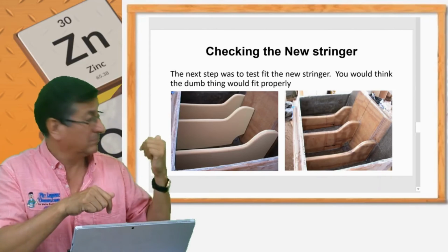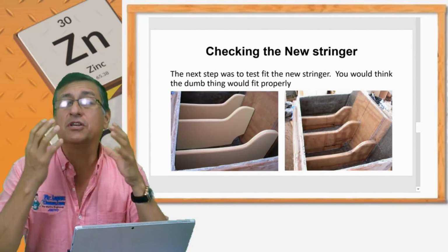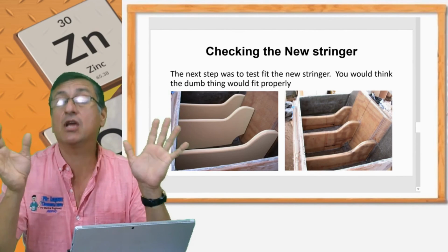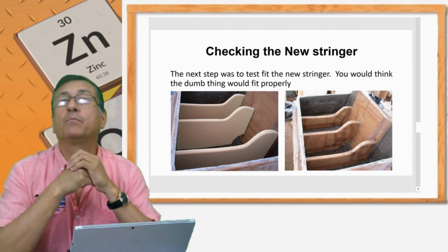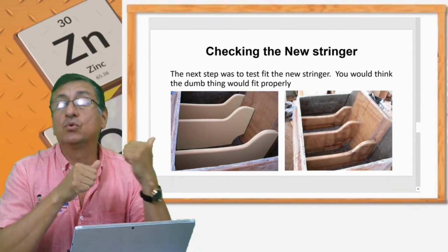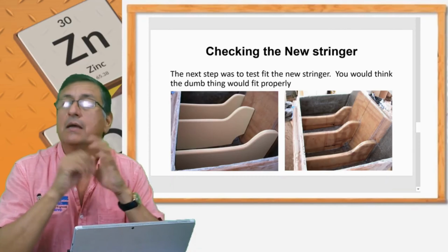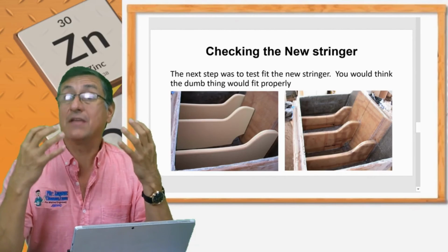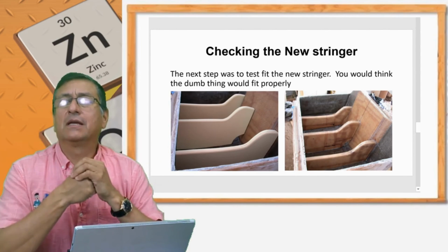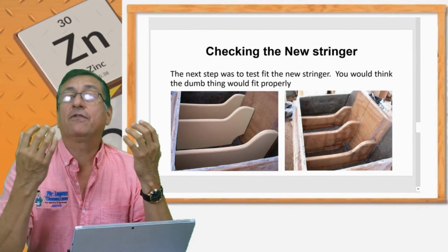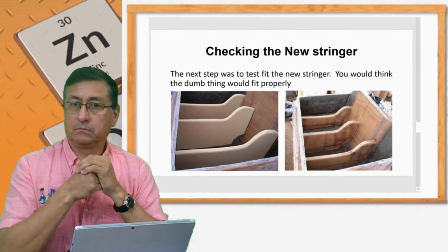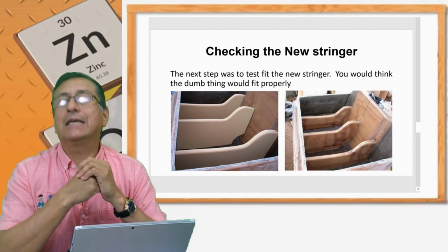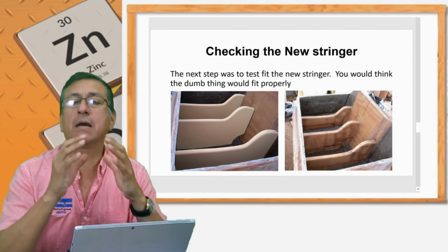That reparation is, in some cases, more expensive than buying a new boat. For that reason, the majority of the people put the boat in the garage because this is too expensive. Okay? Be careful with that. The life of the boat depends on the condition of the bonding system, the protection. The life of the boat depends on how clean is the boat, how protected is the boat with the proper sacrificial anodes. Yes, my friend, this is the most important part in a boat.